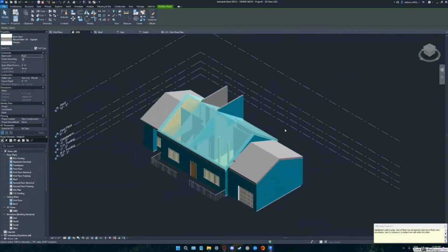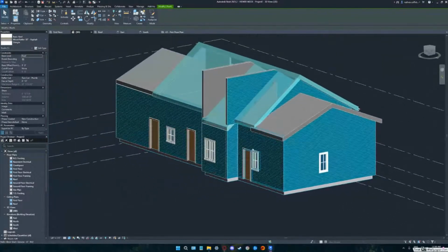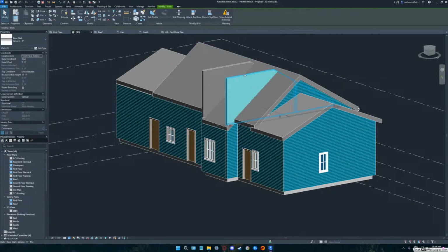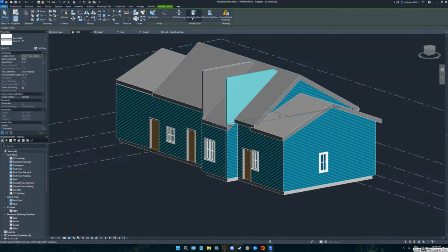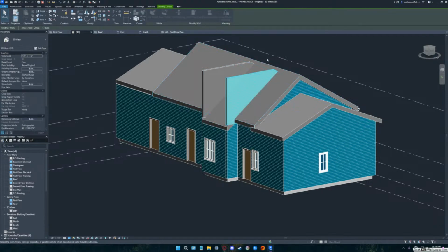Go take a look at it. And all you have to do is attach those 2 walls to the roof, and it would fix it. Oh, pick just one wall. Pick one. You got to pick one wall at a time in order for that attached top to work. You pick the wall, then you say attach top, and then you pick the roof. Okay. Attach top, roof.